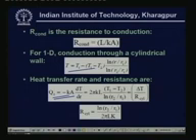Again, you can write this as delta T by R cylindrical, where R cylindrical is the conductive resistance in cylindrical coordinates. In cylindrical coordinates, the conductive resistance, if you compare these equations, is given by ln(R2/R1) divided by 2 pi L k. In this equation, R2 is the outer radius of the cylinder, R1 is the inner radius of the cylinder, k is the thermal conductivity, and L is the length of the cylinder.